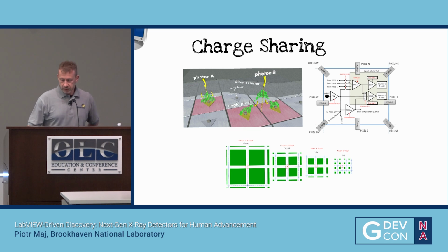Let's sum all the data together and then put comparators between a certain channel and all the neighbors. Sounds easy, but the pixel size usually is less than 100 micron. So the solution is really squeezed inside. Then we have an idea how to verify if it works fine.